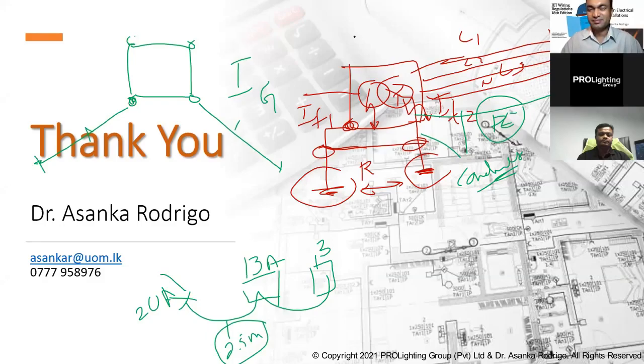Thank you, sir. The question is regarding the residual current protection in data centers. I have met clients with no likelihood of having any residual current protection for their data racks, because they don't need any tripping. To maintain 100% uptime, they need to avoid residual current protection. I just need to know whether BS allows going without residual current protection. The BS allows it in those types of locations. Those are considered special installations, where you can go with an isolation transformer.